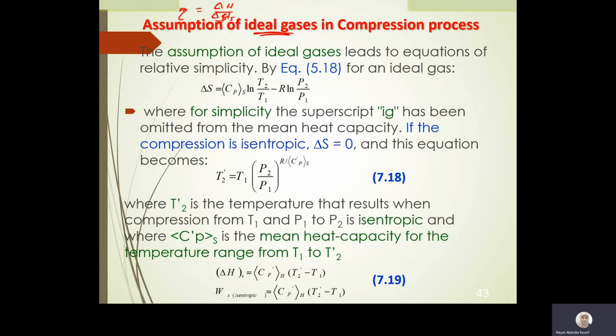And to get delta HS, what we had to do, we considered an isentropic process and we solved. Same thing here. For an isentropic process means what? Means delta S is equal to 0. And when you say delta S is equal to 0, if you rearrange it, you will get that equation. If you remember, we already did such a derivation in the previous chapter. And I mentioned to you that this came originally from the delta S equation.